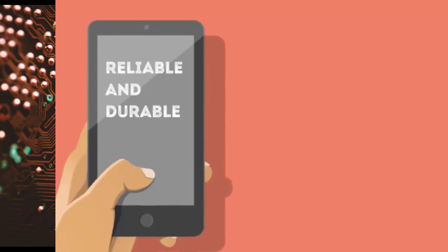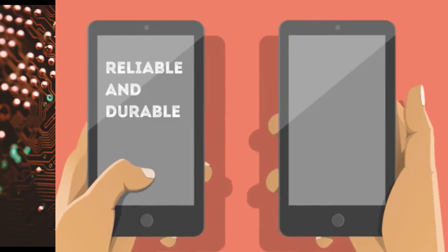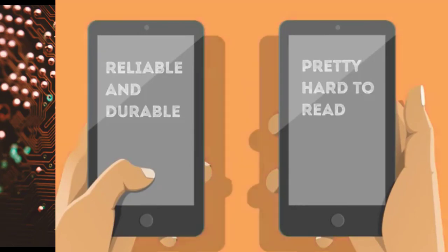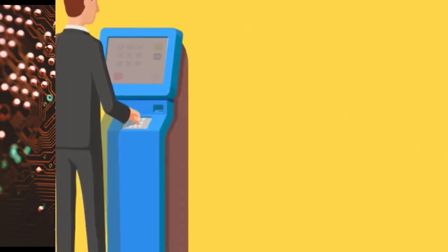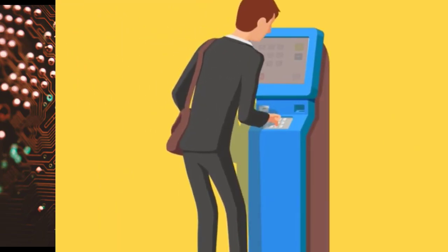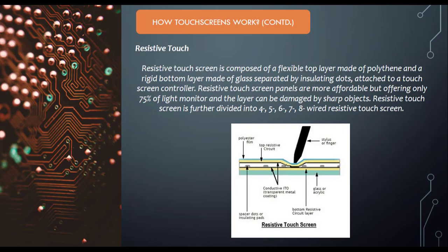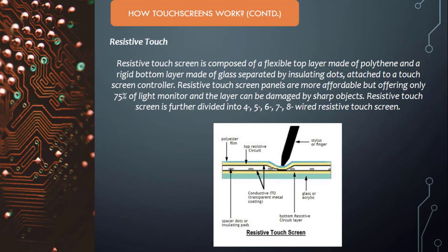One of the advantages of these resistive touchscreens is that they are inexpensive, have better resistance to dust and water, and can be used with gloves. However, there are some disadvantages as well. They have low touch sensitivity, are unable to support multi-touch, and have poor visibility in sunlight. The touchscreens that you use at a local ATM or the automated supermarket checkout are resistive touchscreens.